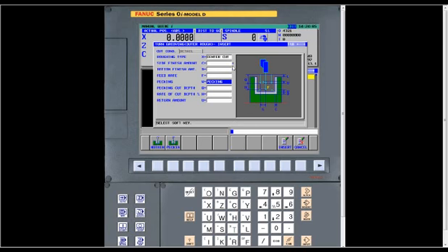A feed rate, a pecking. You can tell it to peck, where it just goes in so far, backs out, where it will break a chip. This is very handy for grooving because we've all been down that road where we do a grooving cycle and we end up with a chip that's about 3 miles long. We don't want that. This is very powerful. It gives you a choice of where you can get around that.